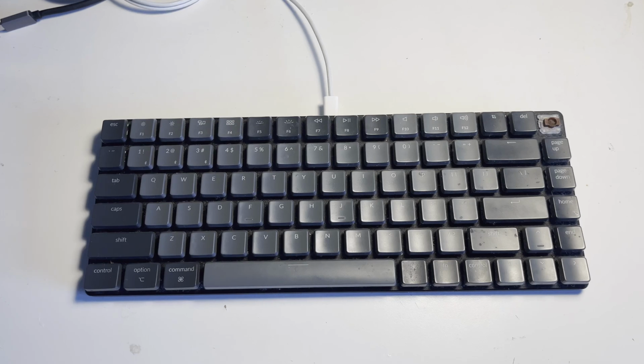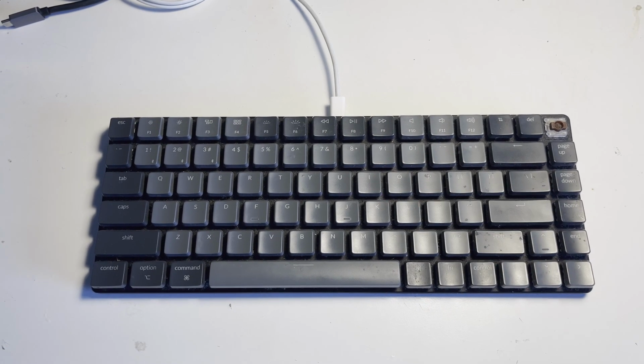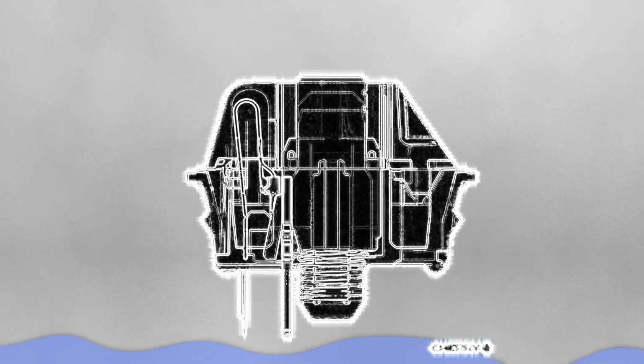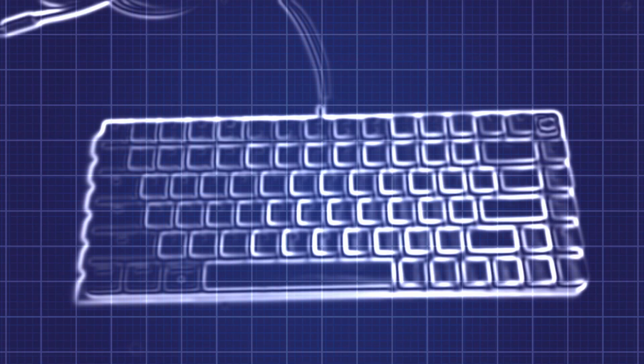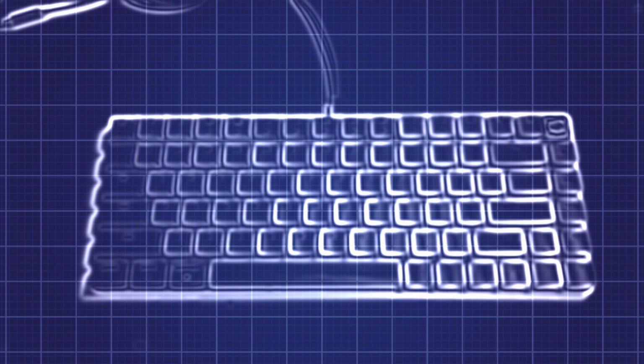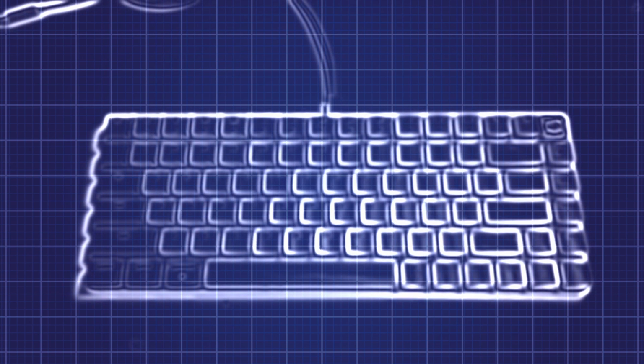It begins with the press of the Enter key. Beneath your fingertip, the keycap pushes down on a mechanical or rubber dome switch. At that instant, two metal contacts touch, and a small current flows through copper traces on the keyboard's circuit board, signaling that the key is closed.